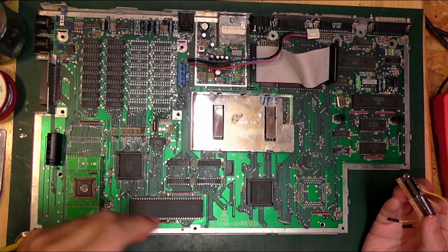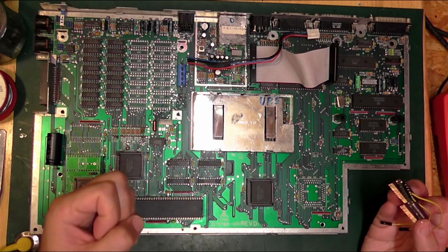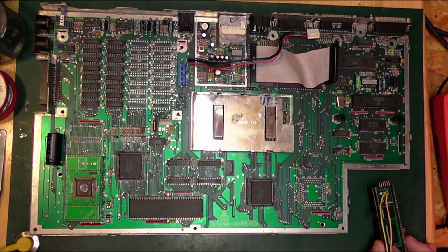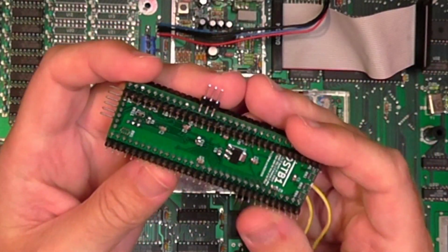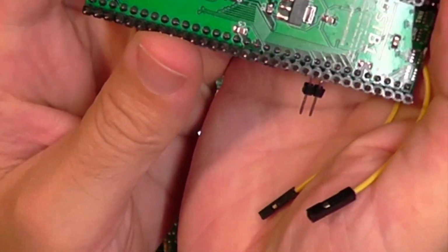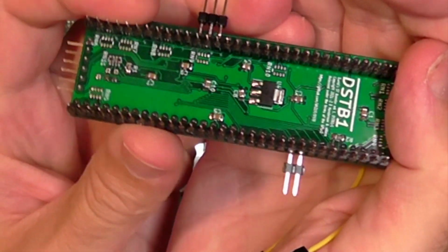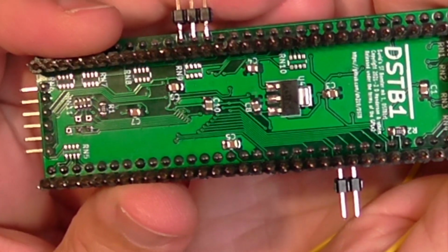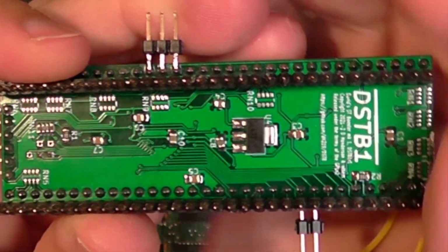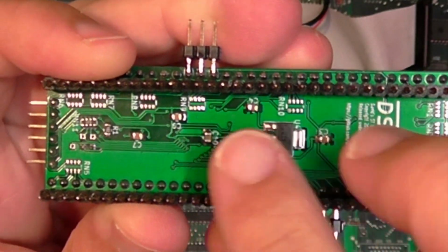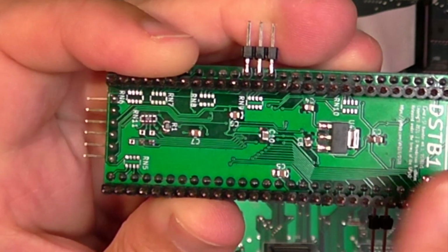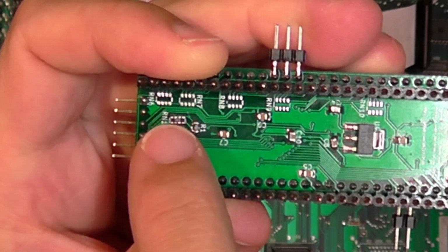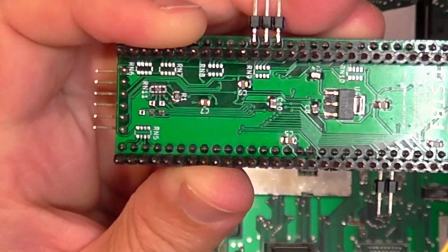When I say lower, I mean higher in terms of resistance, the lower limit of what is feasible or what is realistic in trying to stabilize those oscillations. So on my DSTB1 board, for example, you can see that there are positions on the board here for resistor packs. There's resistor pack 10, 9, 8, 7, 6, around there, another one down in the corner here, which are not populated on this board. I've only got one on the board, which is actually doing a vital role.